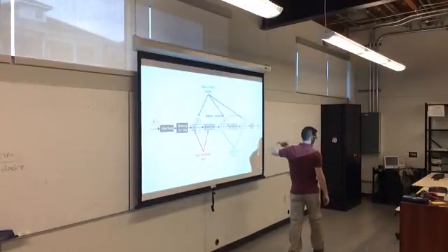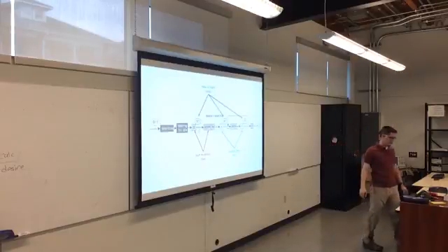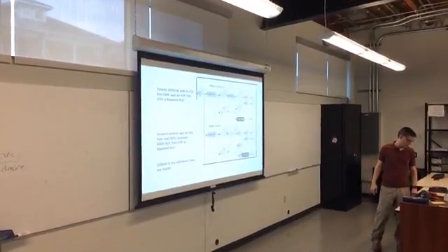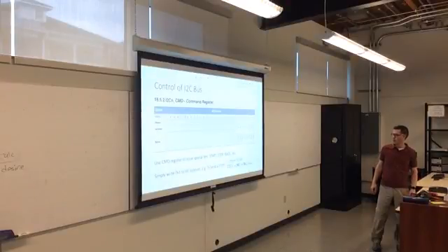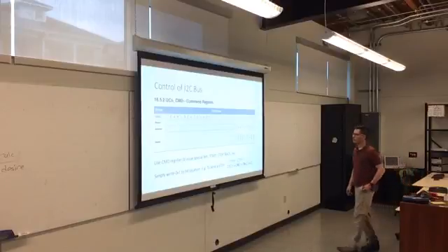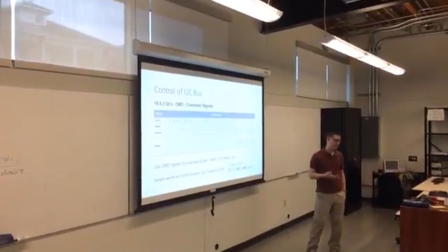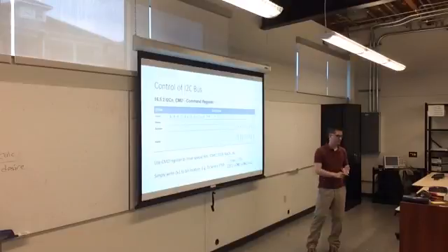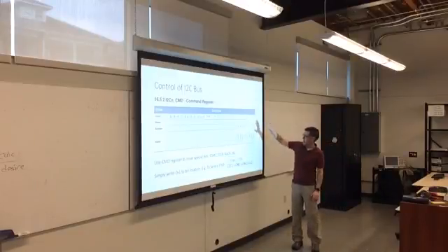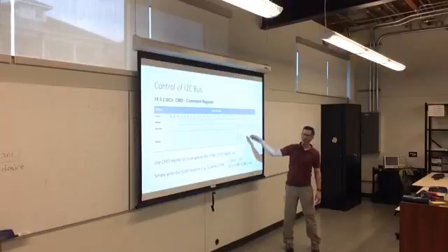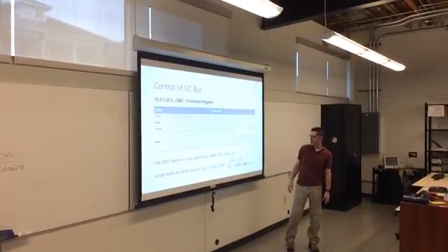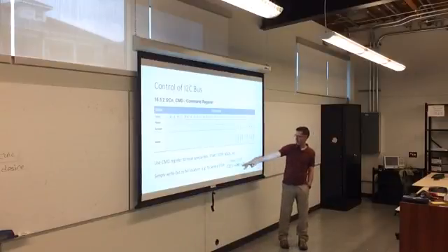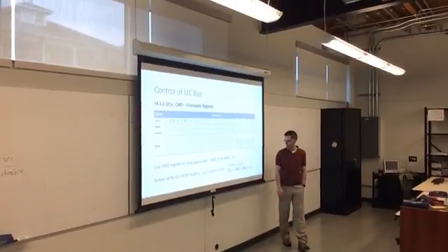The way this looks is, to do all of your actions except send data, to send all your start bits, your stop bits, your NACKs, your ACKs, there is a command register. And in the command register, you can say what actions you want to take place. So if you wanted to send a stop bit, you would put a 1 right here. And so you would put a 1 in the bit 1 position, and that will, boom, when it's time, send a stop bit.